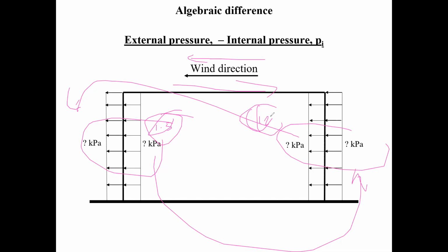On top of that, what you're actually doing is designing for the studs along the edges. That's where the wind pressure is the highest. Here they're lower. Are you going to redesign them for those? No, because if they're good for here, they're going to be good for there in plan view. I leave these blank, and it's almost as if you draw a blank in your mind.